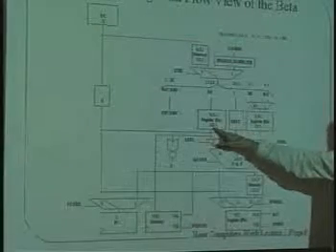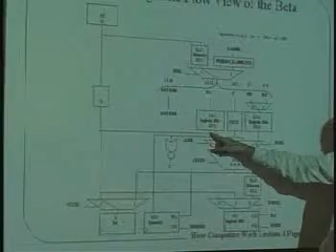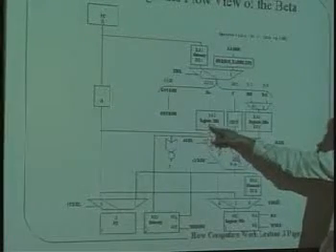RA1 results in RD1. The address goes in here, a number between 0 and 31, and RD1, being a 32-bit data item, pops out of here, which is going to be the contents of the register specified by the 5 bits that go in here. In a similar way, here's another port on that same register file, and 5 bits are going to go in here and say what RB is, and that register data will come out of the bottom here. And so what will pop out of here is the contents of register A and the contents of register B.